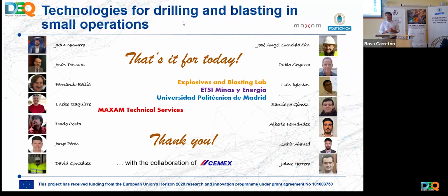One I was explaining was the crosslinker. You have an explosive that is crosslinked that will not migrate through cracks, that is water resistant. At the end, you are reducing the migration of ammonium nitrate liquids into the field, into residual water that could be filtrating into the soil. So you are helping to secure the environment in this way.